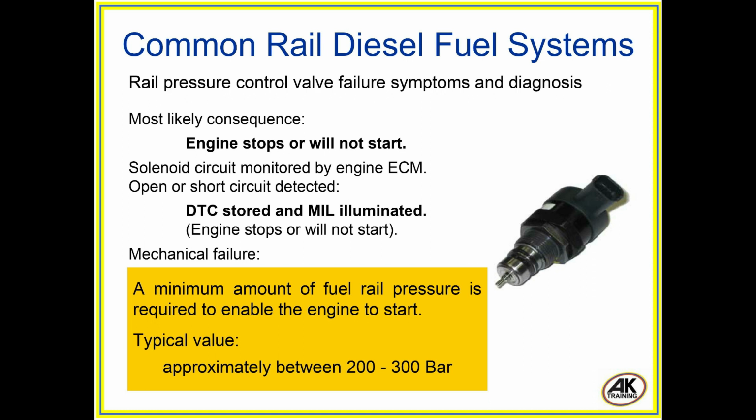Mechanical failure. A minimum amount of fuel rail pressure is required to enable the engine to start. Typical value, approximately between 200 to 300 bar.